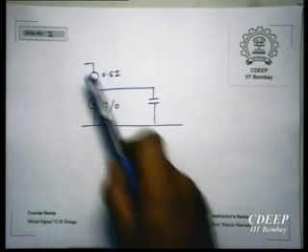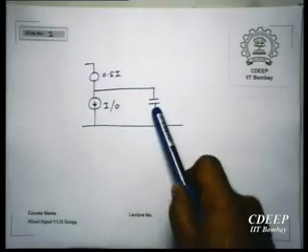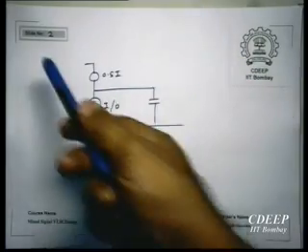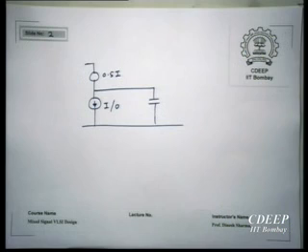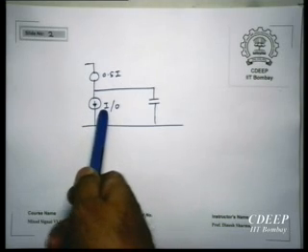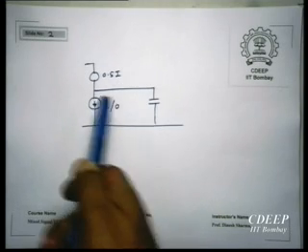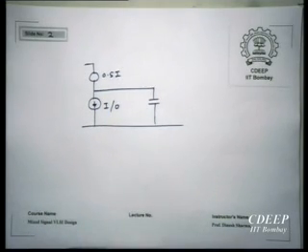This current will charge up this capacitor towards VDD till this current source switches off. Okay. On the other hand, if it is I, what happens? A net current of 0.5I discharges this capacitor. So the output will be rail to rail till the transistor switches off, right? So that is very nice.